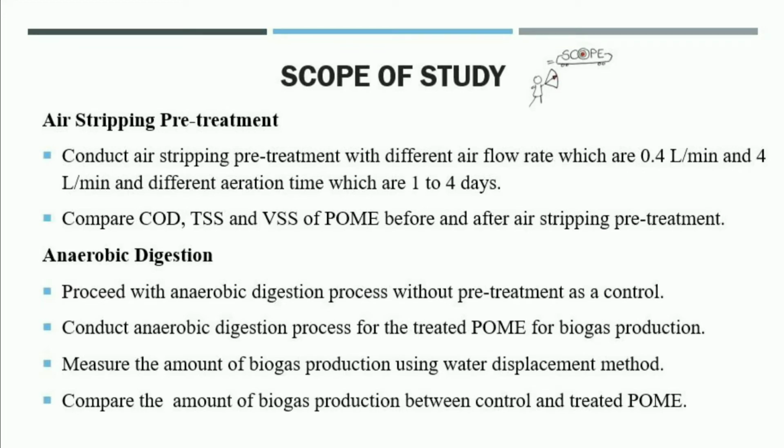For air stripping pre-treatment, it will be conducted with different airflow rates, which are 0.4 liter per minute and 4 liter per minute, and different aeration times, which are 1 to 4 days. Then COD, TSS, and VSS of POME before and after air stripping pre-treatment will be compared.